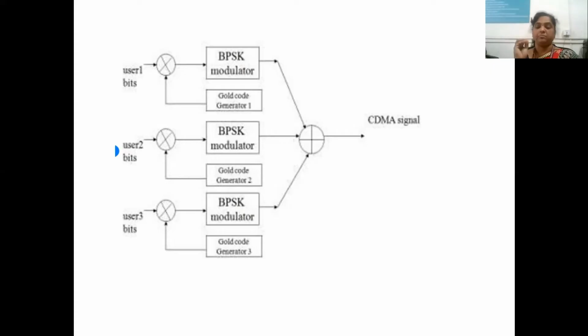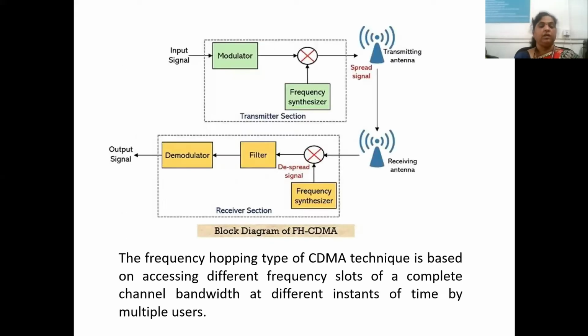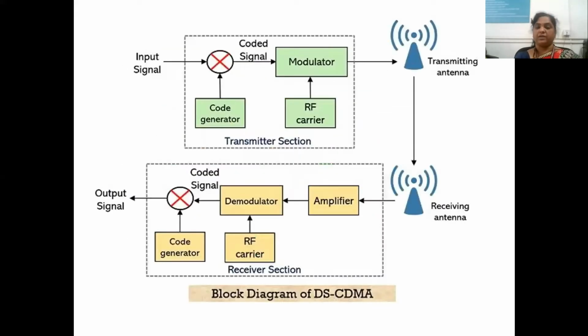So your data is going to be kept secure as the PN sequence generated, or the security code generated, is nothing but a unique code. And then it is transmitted on a single carrier, that is the 1.22 megahertz carrier that is used in CDMA. Now basically the technique which we have seen is this direct sequence spread spectrum technique.